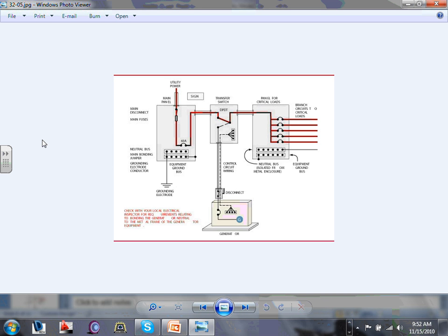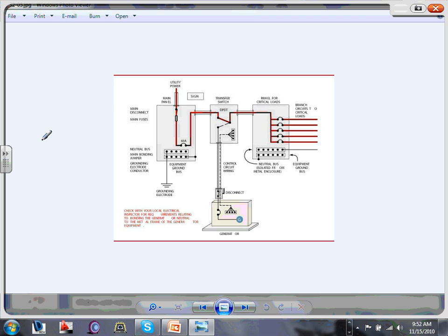So look what they did here. In between the sub panel and the main panel, they introduced an auto transfer switch. Normally, if you look at the power, the auto transfer switch, or the manual switch, could be manual or auto. Look at how it's connected to the utility side. Here's my 60 amp coming through an auto transfer switch, feeding this sub panel. The system right now is a normal system. This is a sub panel fed from a panel. Do you guys have an issue with that? No problem. The way it shows right now, it's a sub panel fed from a panel.